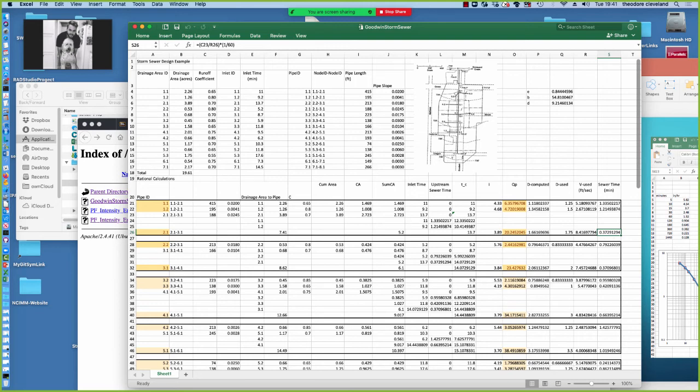So far we've sized this pipe, and this pipe. So 3 pipes have been sized in this first grouping of computations. Going to the second grouping, we're going to size pipe 2-2, which is this pipe. Make sure this goes from 22 to 31. We'll size this pipe 22 to 31. So that's a remote pipe, a lateral coming into the main, and then we'll size pipe 31. So let's just first do this pipe 22 to 31.